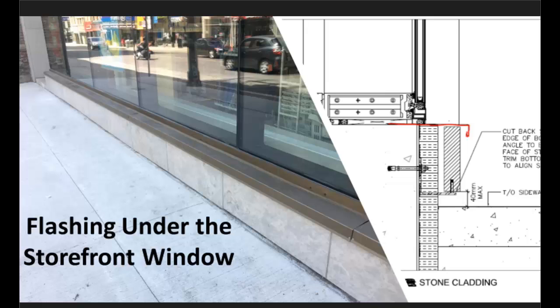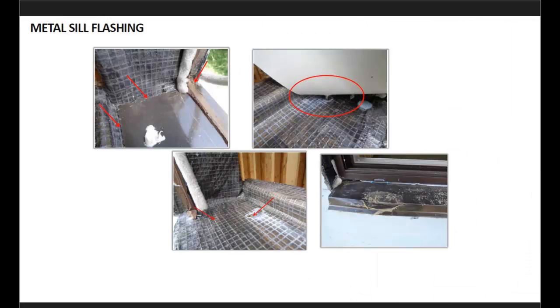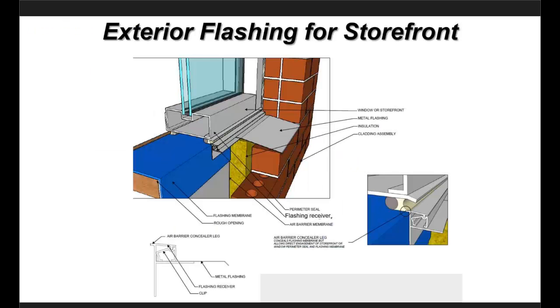If you're working on something that has become a headache because they don't know how to attach the storefront flashing, I've got a solution for you. It was actually designed by a consultant in the area who works with general contractors. They said this is becoming an issue on every building, and how we've been doing it is just shoving it under the storefront. We're interrupting the perimeter seal. It's not easily replaced if there's damage. It's a thermal break issue, performance, sequencing, a whole laundry list of items.